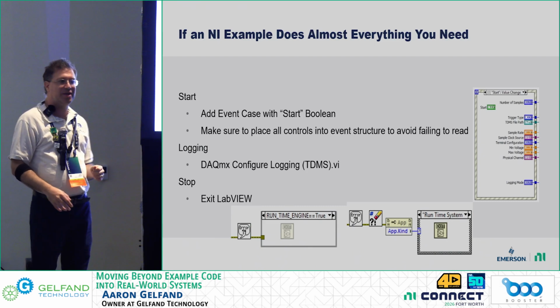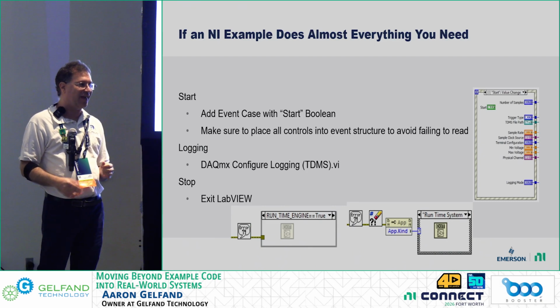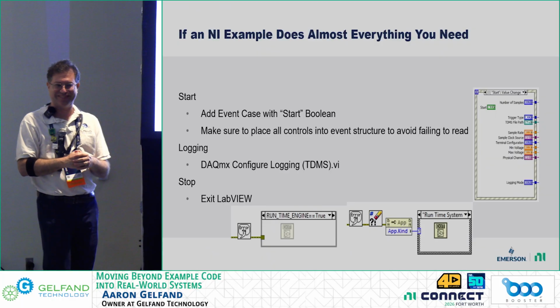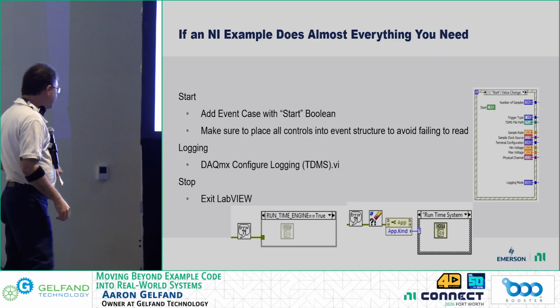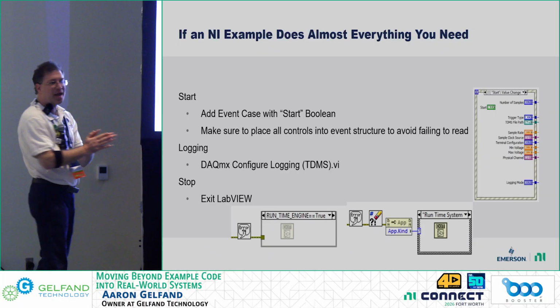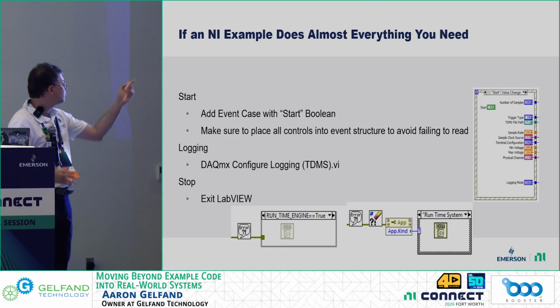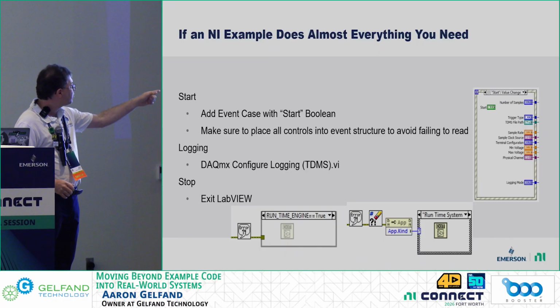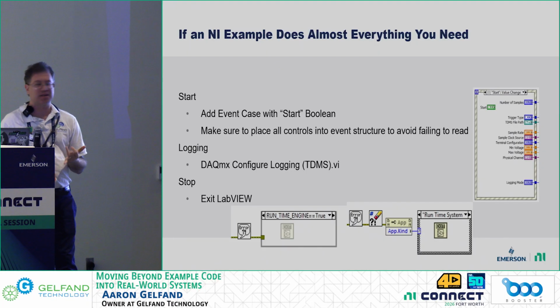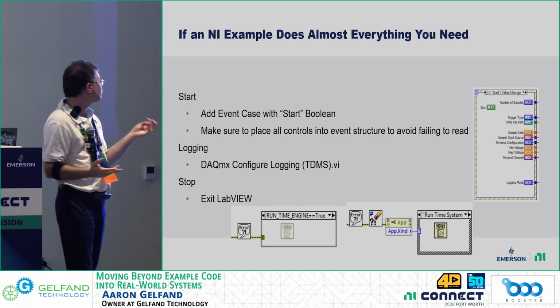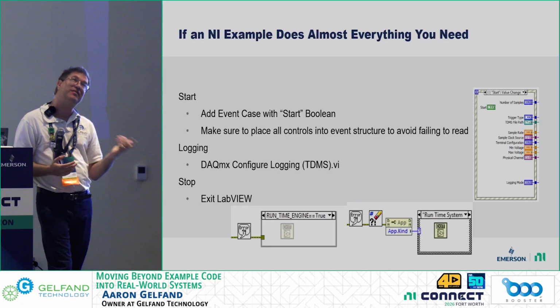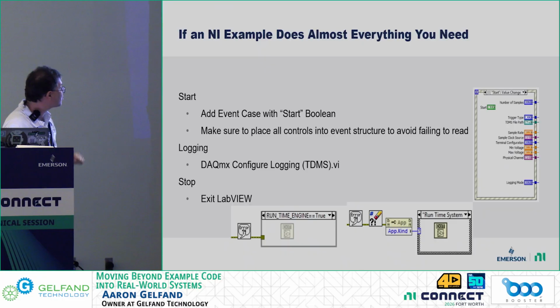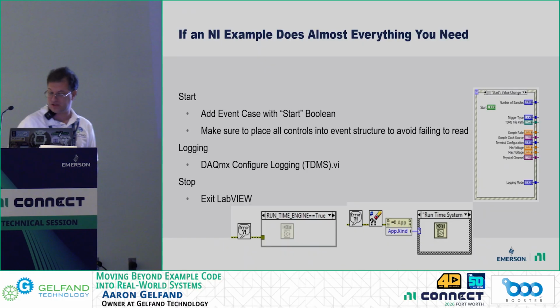We can put that there and we don't have to worry about LabVIEW quitting on us every time. An alternative approach is to drop a property node, set to application, and you can have Application Kind that gives you runtime system, development system, invalid, and a couple of others, and we can just put our exit in that case structure right there.